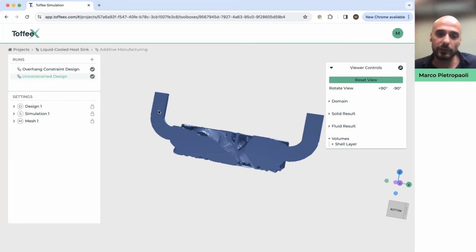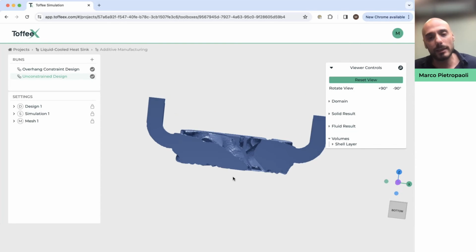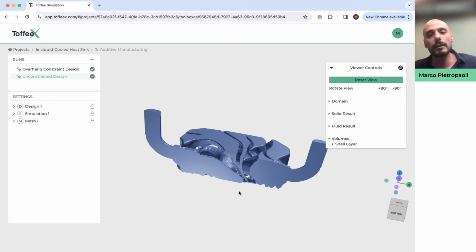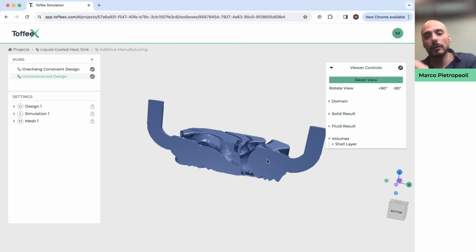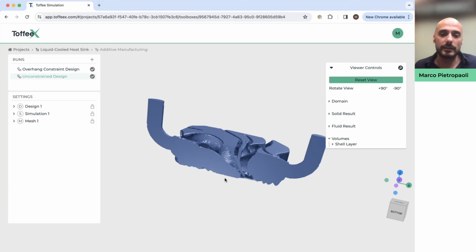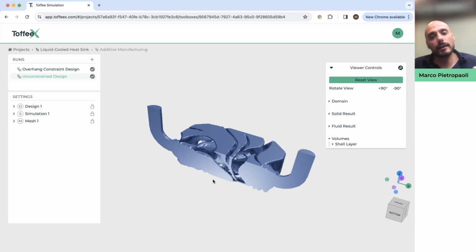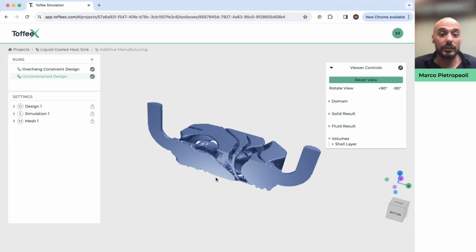So the fluid enters from the inlet. It's breaking into all these small channels, and once it gets warm against the hot wall, it is reconvected out to then leave the component. This is done in an efficient way because it's balanced with the pressure losses. So you won't see a big recirculation region. You won't see, let's say, a sharp corner, because the optimization is driven really by the streamlines. This is guaranteeing high efficiency in thermal extraction while maintaining very low pressure losses.